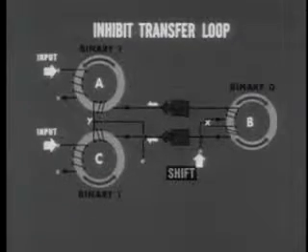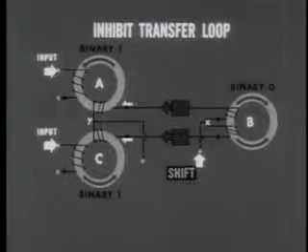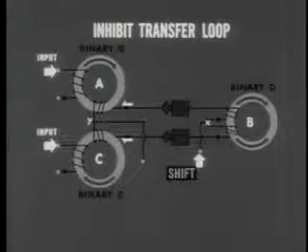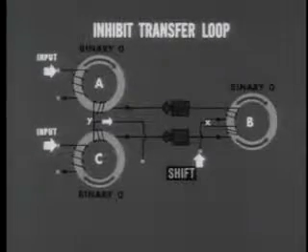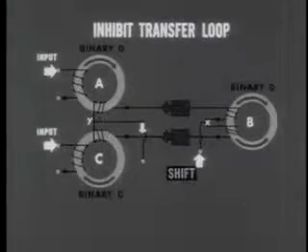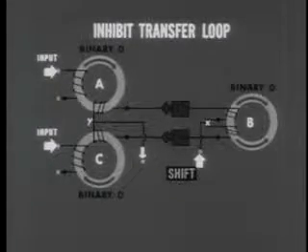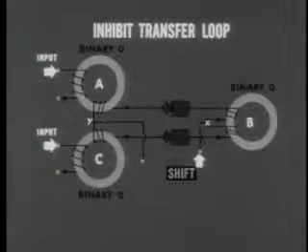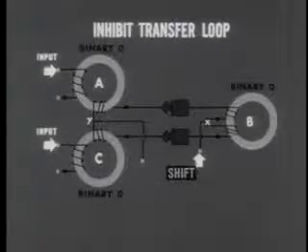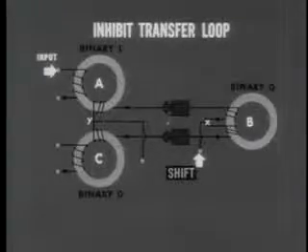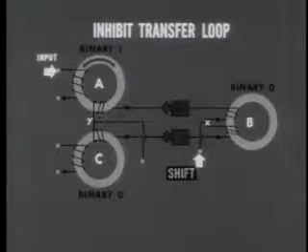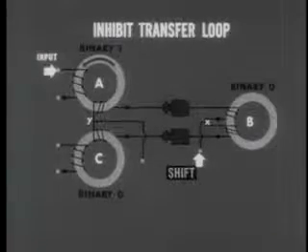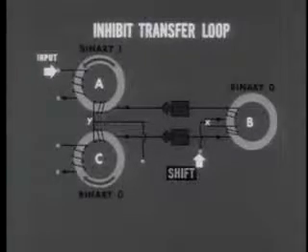At core A and at core C, they come in as dot pulses and switch the cores to 0. The two branches join at point Y and flow out of the circuit. Thus, the shift pulse cleared cores A and C, but it was unable to transfer the 1 from A to B. To achieve a transfer, we'll apply the input to core A, but not the input to core C. This switches A to 1 with its flux in the positive direction, leaving C at 0 and its flux negative.